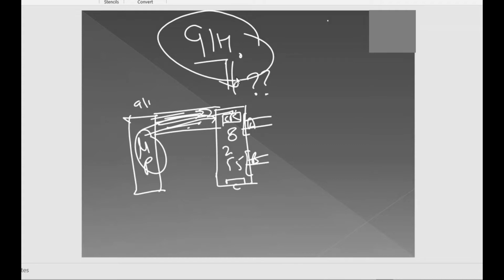So inside, 91H has a configuration like A acting as input, B acting as output, likewise for port C, upper and lower. Now, as soon as it is set inside the control register of 8255, they all will be configured according to the configuration which was prescribed or decoded earlier. Fine, understood? Yes, sir. Okay, so this is how the 8255 communication is established in the microprocessor domain.